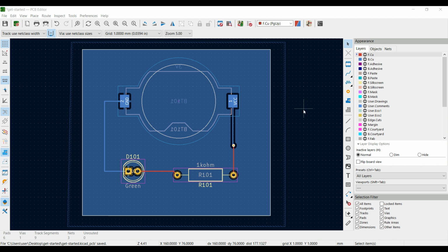Design rule checking is the layout equivalent of electrical rule checking for a schematic. We have done the electrical rule checking in the schematic editor while designing our schematic. Design rule check, shortly called DRC, looks for design mismatches, like mismatch between the schematic and the layout, copper regions that have insufficient clearance or are shorted together, and traces that do not connect to anything. Custom rules can also be written.